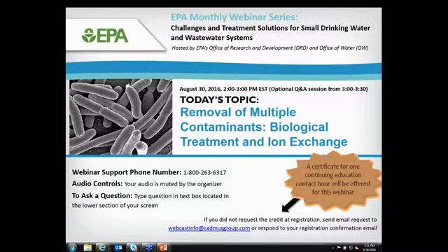But we have run filters, dual media filters, and we've run reaeration units and dual media filters downstream of anaerobic biological contactors, for example. And we've shown that we can consistently produce finished water that has dissolved oxygen back to saturated concentrations, has filter effluent turbidities that are less than 0.1 NTU, and which, when chlorinated to hit a residual of 1 milligram per liter after 24 hours of holding time at a pH of 8, was consistently in compliance with the Stage 2 disinfection byproduct rule standards for trihalomethanes and haloacetic acids.